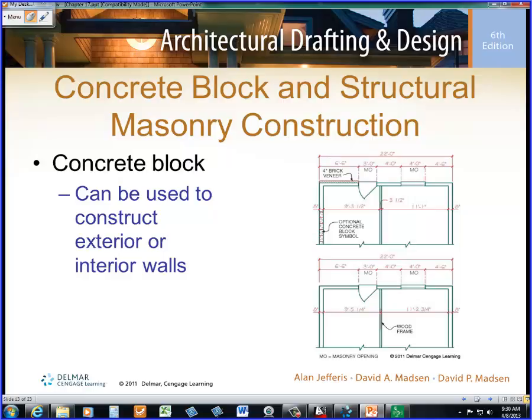Now if it's a production kind of drawing for layout, a layout drawing that carpenters are going to use, kind of a combination drawing but not a finished drawing showing all the finishes, then you might have dimensions like this, and we would dimension to the edge of each feature. I want you to make a note in your mind though, they're showing this as a concrete block and it's 8 inches thick. Well, concrete block is not 8 inches thick, it's 7 5/8 inches thick. So they're showing a nominal size here, and an actual size dimension here.